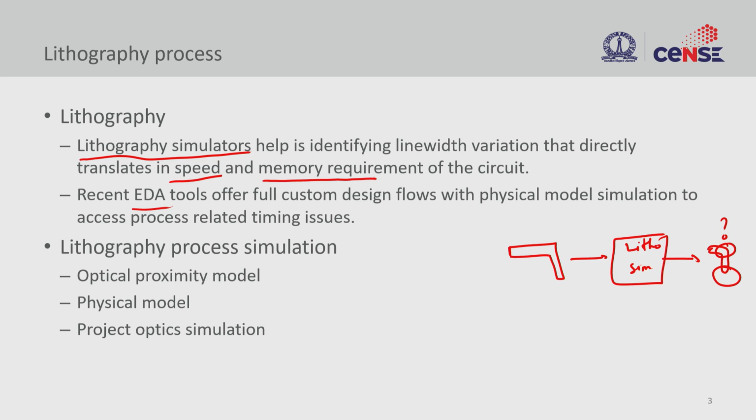And if one block is relatively slower than the other, you might miss the timing, and then your whole logic is not going to meet the requirement, right. So here you want to understand whether your timing will be affected because of the physical design you have, or what is the margin you have. All those things could be done using present day design tools.